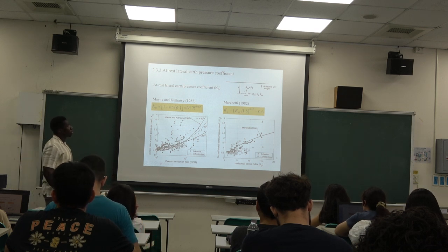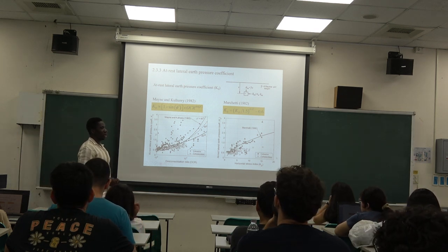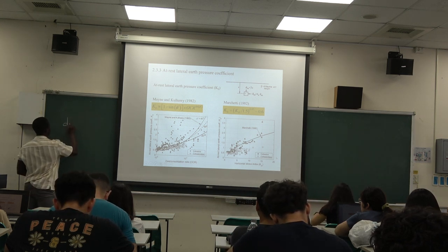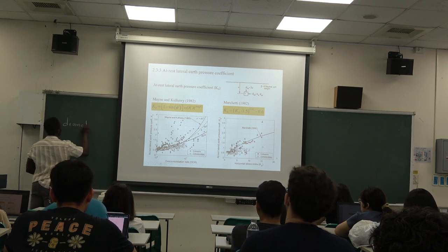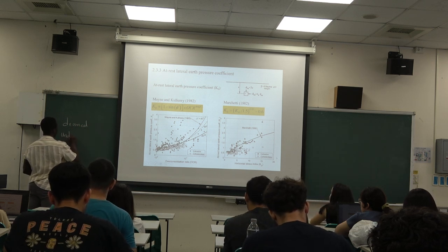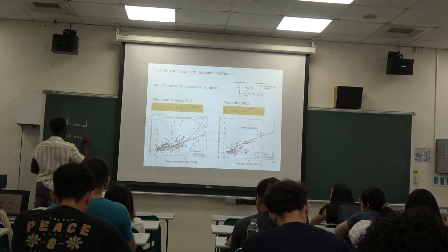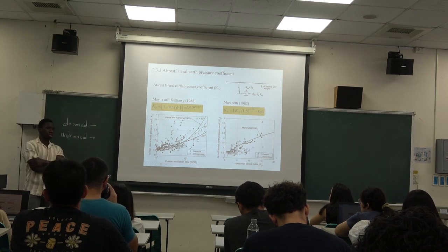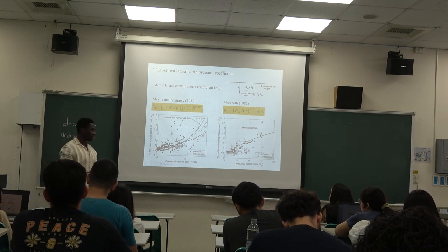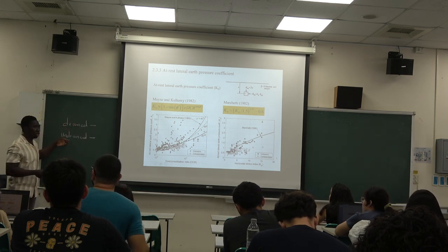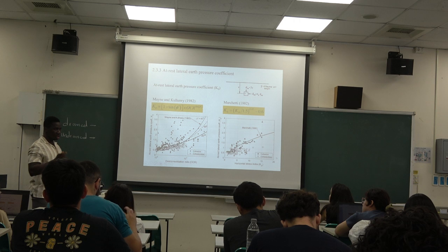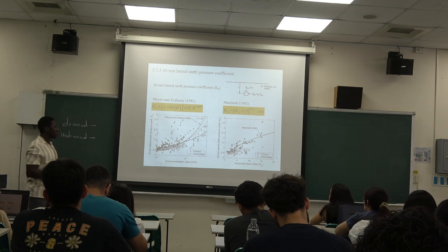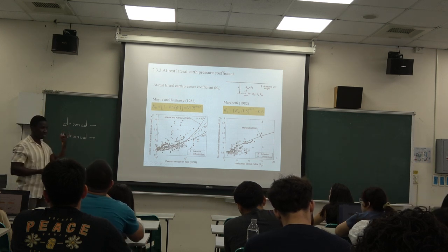So yesterday we basically talked about two major things. We talked about the drained analysis and the undrained, right? For the drained analysis, we say mostly it is the coarse grain soils, for example, sandy soils. They will be in the drained condition. And for the undrained, we talk about the fine grain soils, for example, clay and silt. And we say the principle here is actually very, very simple.